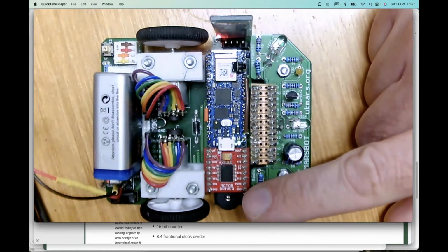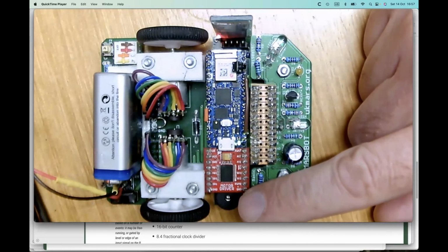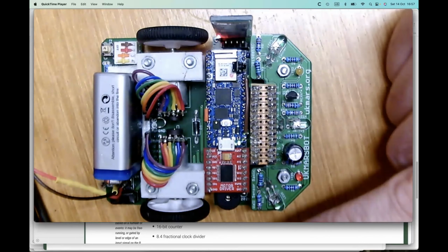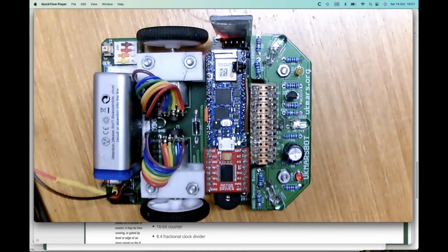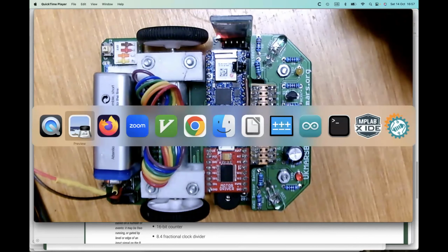But for making tones, obviously you want your cycle time to be set at the frequency you want to listen to, and then maybe we set the mark space ratio to be 50-50 to get the maximum volume out.